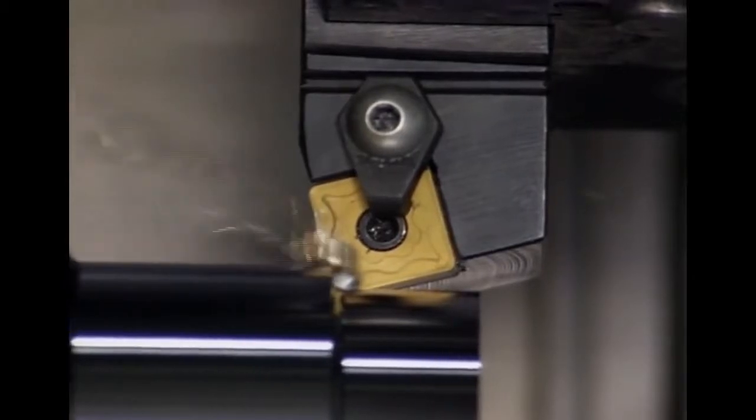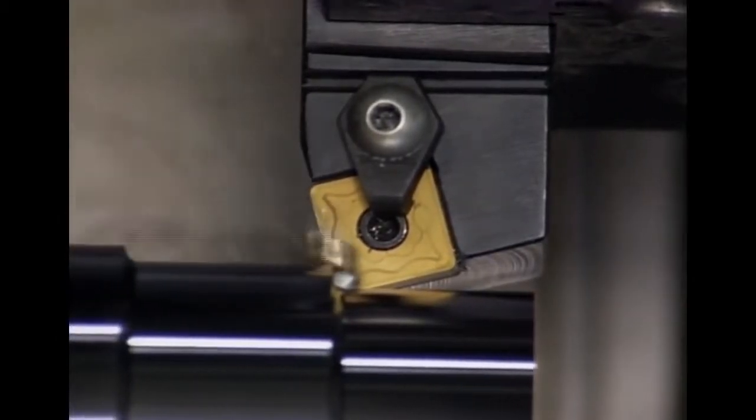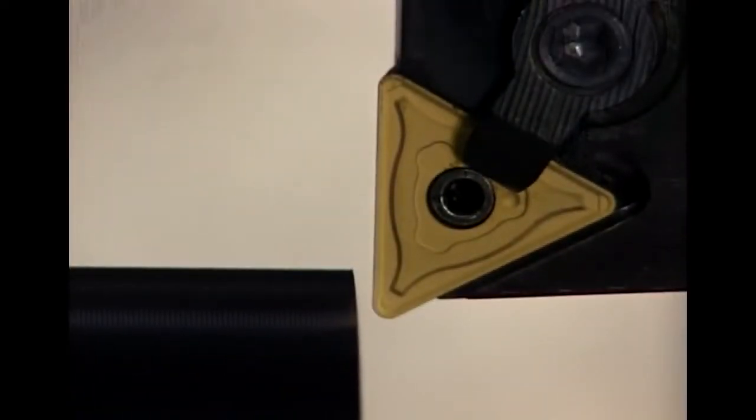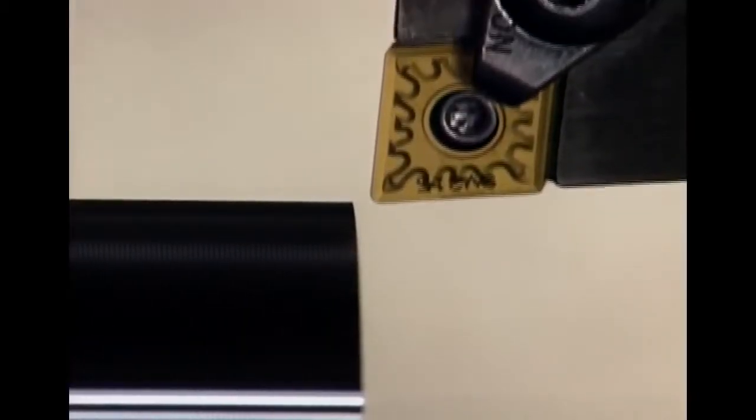This style distributes the cutting stresses, thins the chip, and reduces pressure on the edge. When turning to a square shoulder, the tool holder should have a 0 degree lead angle or a -5 degree lead angle. In boring, a 0 degree lead angle is preferred as it directs the feed force along the axis of the work, minimizing deflection.